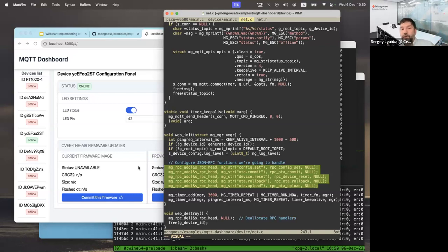So it's quite useful, for example, to define an RPC implementation that configures your device. And then you can export that to a local HTTP and BLE, right? So that you can configure your device using the phone app, or by running the local access point and configuring through the access point.